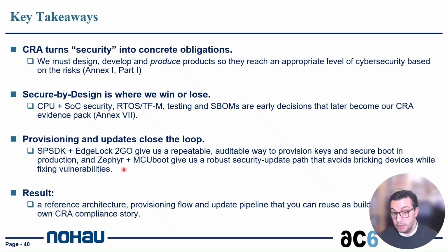And of course, we can use Zephyr and MCUboot, which is very great because it is agnostic to any hardware. So we can use Zephyr and MCUboot and guarantee that for any type of vendor, we are going to cover the same level of security, if it is based on the same CPU architecture, of course. The result is that we have seen here a reference architecture and workflow, a small one, that you can have in your own CRA compliance story.